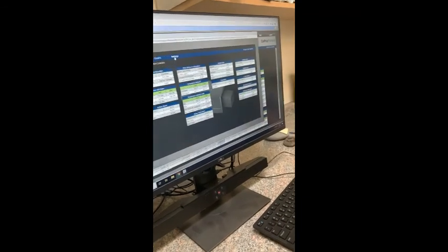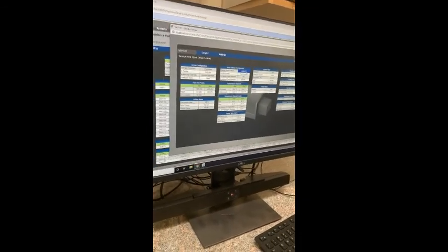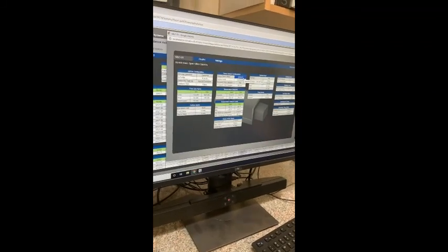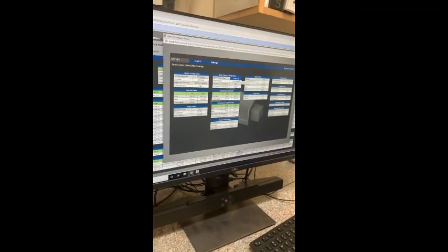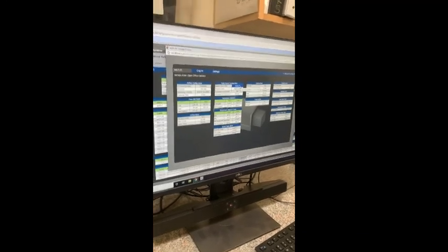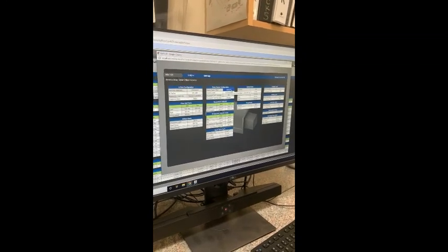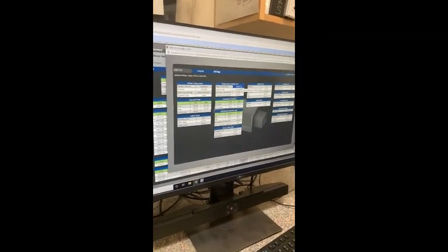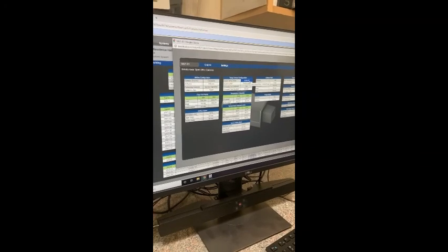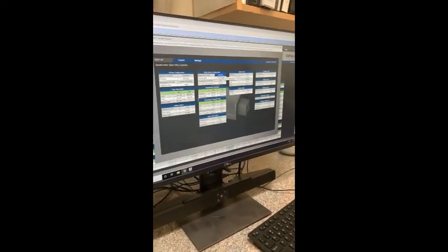And again, we have a settings page for this. From here, if you found in 5 years that one of the room sensors was reading a little off, you could put in a space temp offset. So if you go in, you measure, and everyone else is reading within half a degree, but this one's reading a degree high, you could do an offset there.